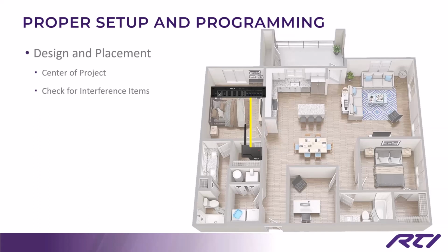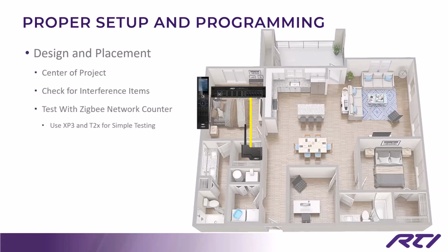After you've taken a look and you've determined that, yes, this is probably going to be the best place for this parent device, then you can test that Zigbee network with the Zigbee network counter. And we'll talk a little bit more about how that Zigbee network test bundle works in just a moment. But just as a little tool of the trade, if you will, the XP3 and the T2X,